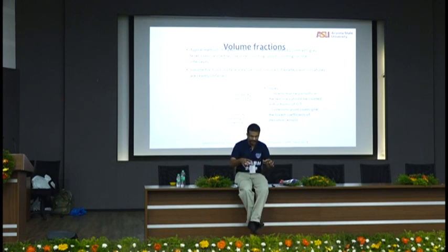So you have this piece of concrete sitting on an XY stage in a microscope table. You take the sample and put it under the microscope. The microscope is all gridded, with grids in the X and Y direction. You turn the knob of the table so it moves one step in the X direction. And once you've done all of that, you do one step in the Y direction so it comes to the next line, like the line analysis I showed you earlier.